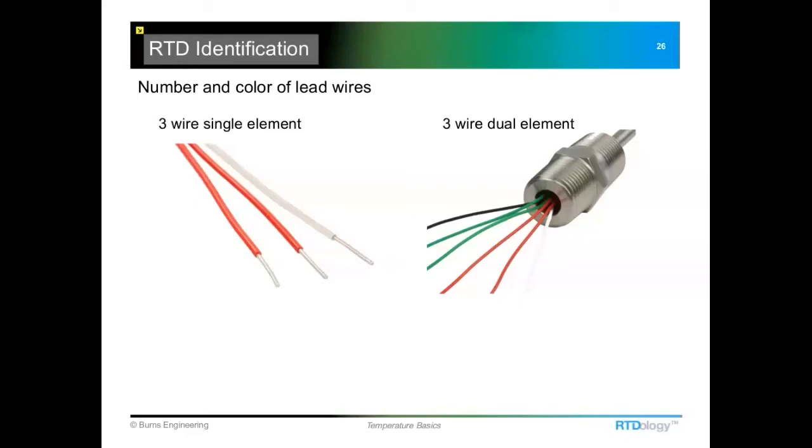All right, a couple other questions. Do RTDs and thermocouples normally creep or drift one direction over another? In other words, do they normally creep up or creep down? Yeah, that's a good question. Thermocouples will generally go up, especially at high temperatures. You're going to see some drift, and it's caused by contaminants getting into the wires, and just how the wires age over time.